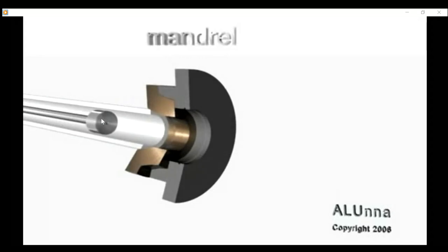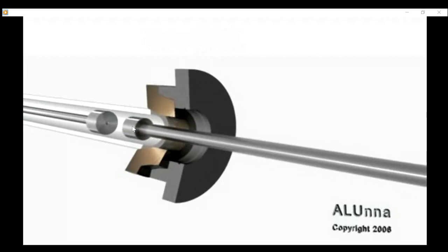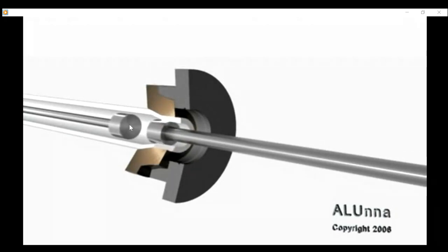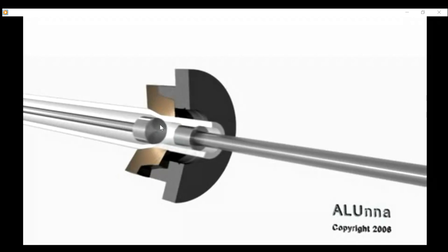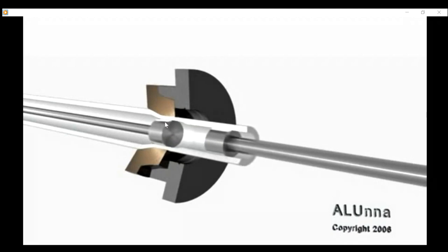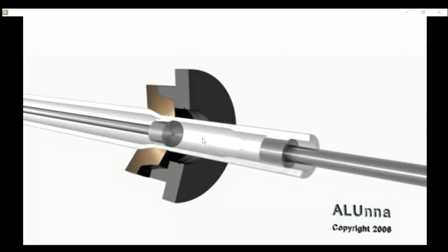When you draw, you destroy the internal shape unless you put in the mandrel. This is the mandrel here. You bring the mandrel here, and the other mandrel is a smaller one. This is the bigger one, the smaller one, and then you start to fix. Sometimes it is movable to fix. This one is smaller than this one, and then you just move. You start pulling this one here, and this one will stop here in a certain area to maintain the dimension. Then you pull it to maintain the dimension. So this is a mandrel.